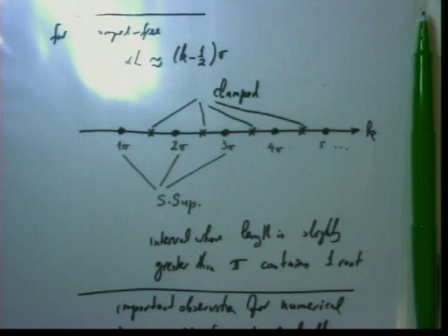So this helps us to do numerical analysis. This 1 pi and 2 pi are associated with simply supported case. So between them there is one star. So between every two dots there is one star. So we can say that if I take an interval whose length is slightly greater than pi, it will contain at least one root for clamped beam.